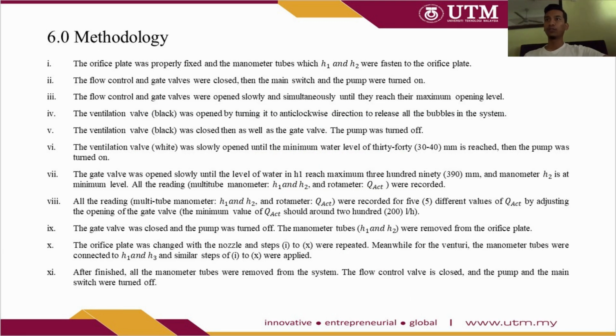Okay, we go through to methodology. First, the orifice plate was properly fixed and the manometer tubes, which are H1 and H2, were fastened to the orifice plate. Second, the flow control and gate valves were closed, then the main switch and the pump were turned on.